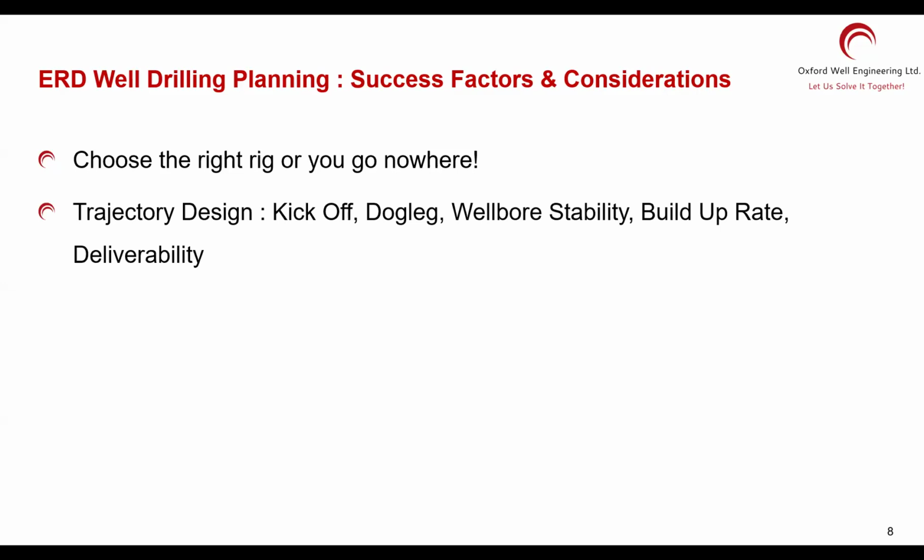I have seen this in action once, and you would be surprised that we had huge problems. Everything was a problem. Surging, swabbing, and things picking up off bottom. We were very close to the limit. And when we pulled out of the hole, some of the connections were a little bit messed up because of the yield. It was reaching the yield of a certain component, like we picked up too hard, or something was going on with the technical limits. So just wanted to say that it is important to be over-designed than under-designed, because that's going to be a huge problem. You cannot fix that problem.